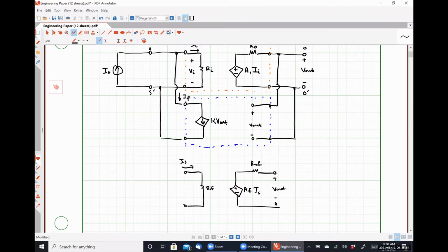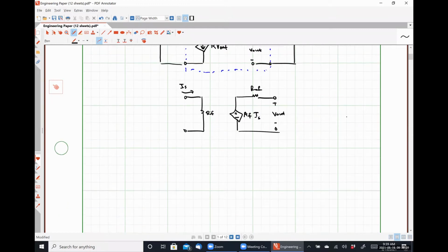We're not going to waste any time deriving literally anything because we know exactly how all of these things behave. So I'm going to ask you guys again for the fourth time, what should our gain with feedback or our closed loop feedback equation be? A1 over 1 plus K A1. Always that. Correct.